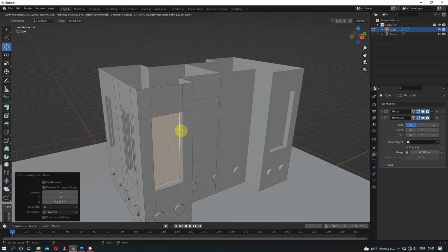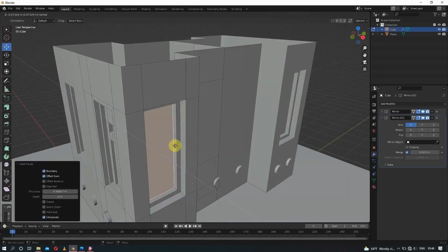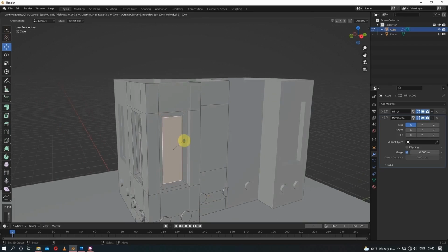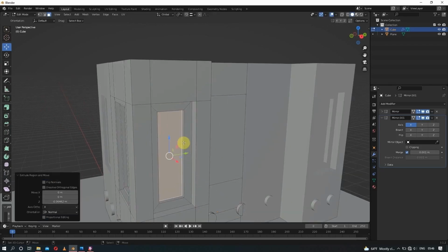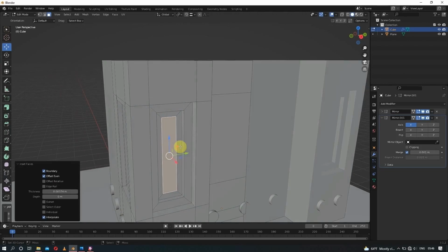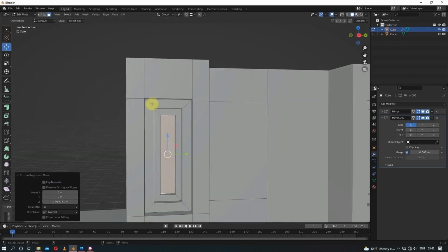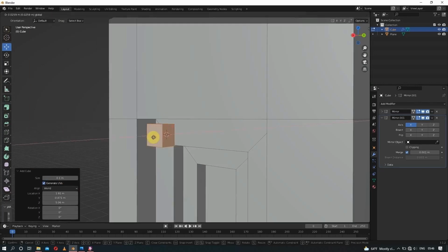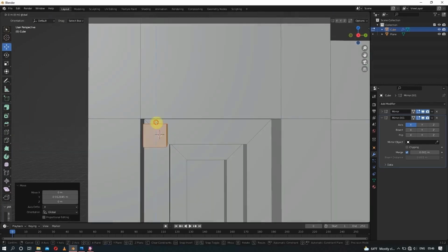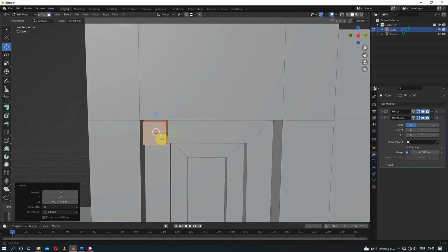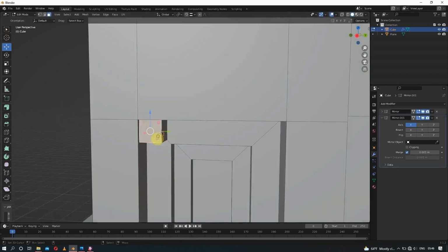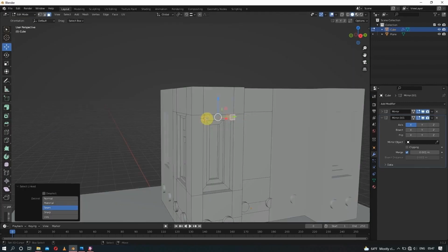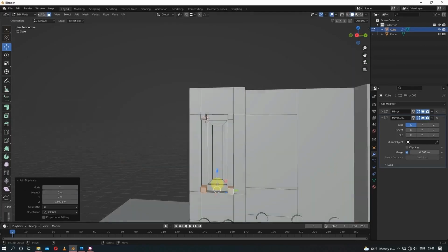So doing the same thing also, insert, extrude inward, insert, and segment the faces. And what's unique about this one is that every time there is a door, there's something called a monkey head that goes on top of the windows and doors, so don't forget to put that.